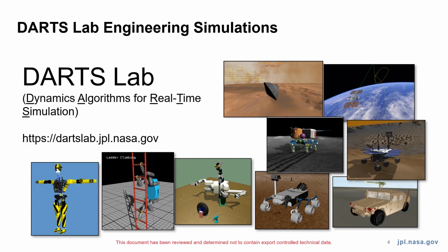At the heart of these capabilities is a simulation framework that includes DARTS for modeling the dynamics of articulated multibody systems, and the generic Dshell framework for putting together complete system-level vehicle simulations on top of DARTS. Our simulations primarily support three domains. First, flight dynamics for spacecraft. Our product Descends is in use for a variety of flight missions and experiments for planning and executing entry, descent, and landing, or EDL. Descends is a primary EDL tool for MSL, Phoenix, InSight, and Mars 2020.